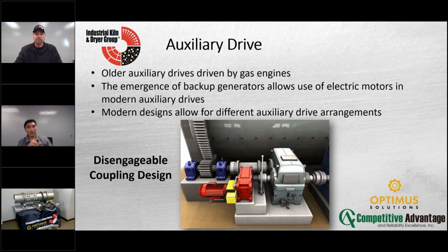Right. And your shell will droop. Your straight kiln shell in the span may become a divot where it's not straight, or what we like to call in the industry a dog leg, or a banana, depending on the region. It could also cause that type of drooping on the tire, or a tire crank, or a tire dog leg. Now that causes other major problems.